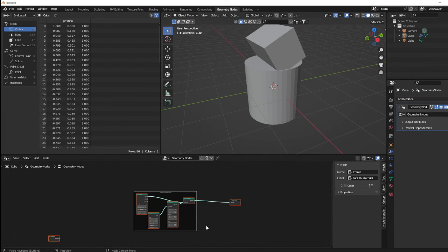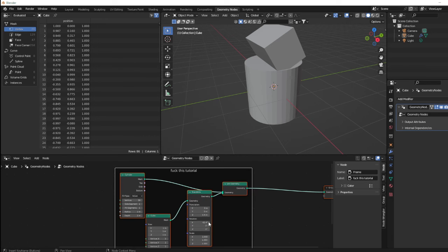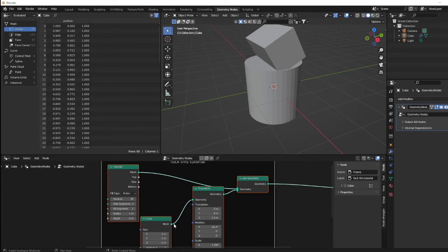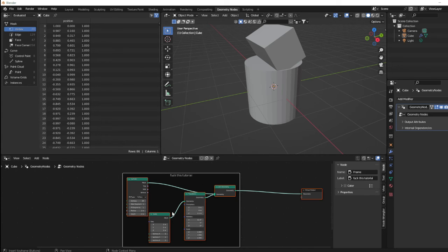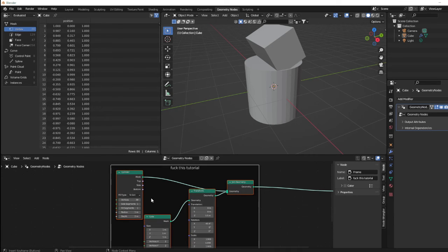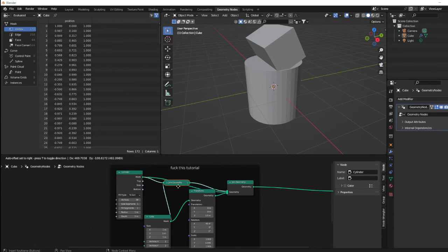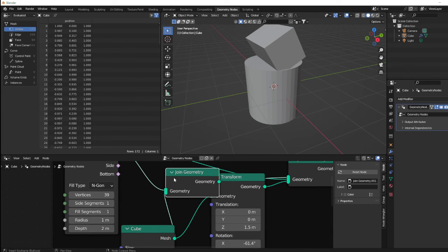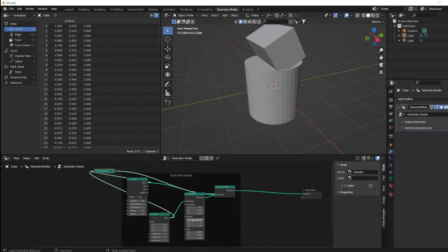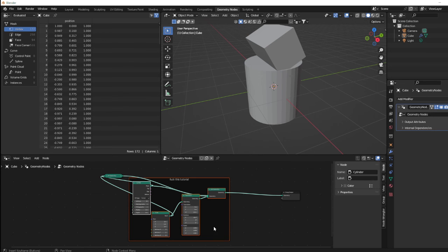This is just basic guys, we're gonna dig more into geometry nodes in the next tutorials, if this tutorial gets views, okay? So, to disconnect, of course, Control, right click and just drag. To connect, Alt, right click and just drag. Of course, using this Node Wrangler add-on. And to join two nodes together, Control, Shift and right click, drag. This automatically creates a Join Geometry node, as you can see. And basically, to create this kind of collection of nodes, select the nodes and Shift P and N, you can rename this right here. Like I said, this is just basics.